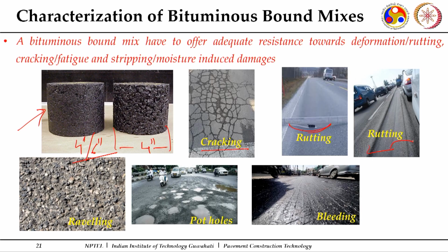This is shown as rutting, where deformation is there. They should have a good bonding with the aggregate. The binder should not become soft enough. So we are going to check finally these mixes, because this is the mix. We have individually ensured the aggregates and binder, and now we are going to ensure the mix also.